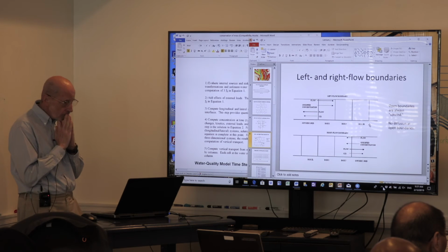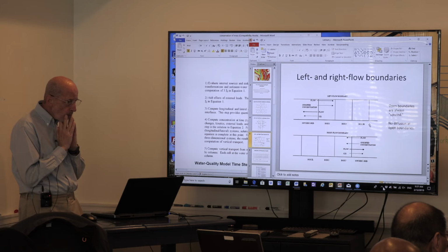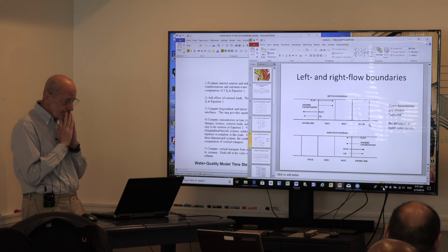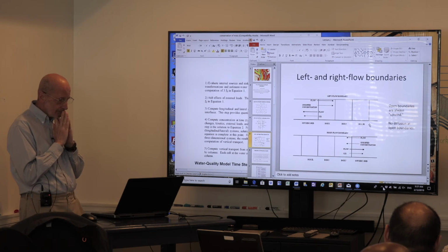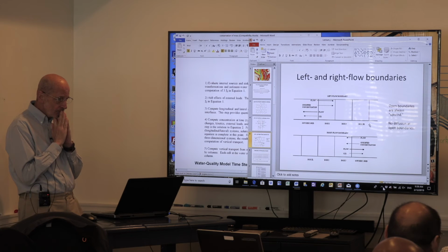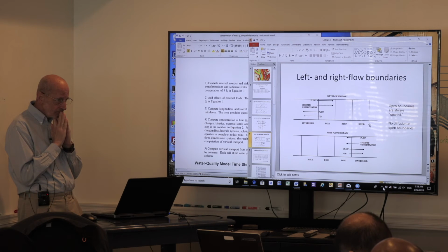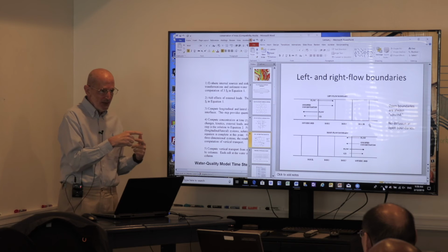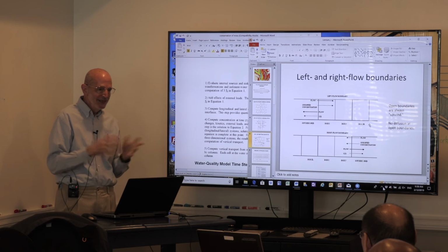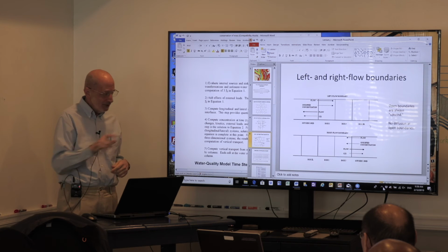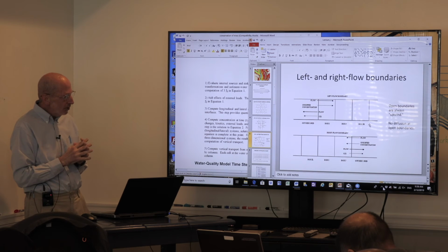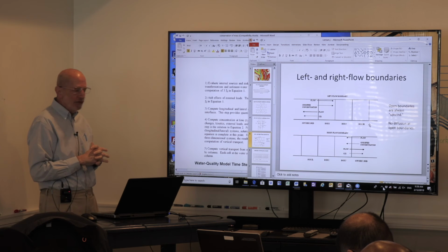Just to expand on that for a moment, what would be the consequences of not having dispersion at an ocean boundary? Well, think about it, since the models are running intertidal, probably not much, but suppose you did a tidally averaged model. Then if the flow was always out of the system, you'd possibly be ignoring some factor of the tides coming back and forth and bringing some concentration back in. So, I've made that mistake. We set up a little tidally averaged model of Linnhaven Bay, and somebody came to me and said the boundary conditions in the ocean did nothing, and it was because we had hardwired no diffusion. And we had to put it back. You had to put it back, okay. Yeah. So that's interesting, but there you go.